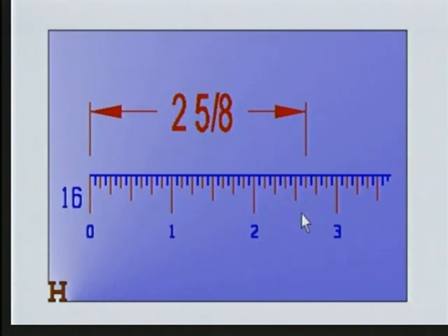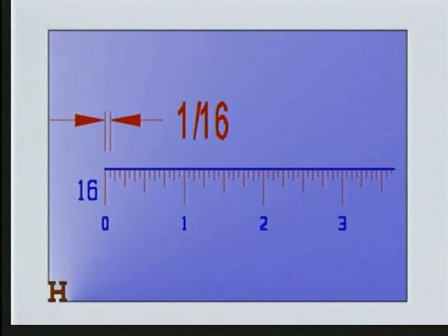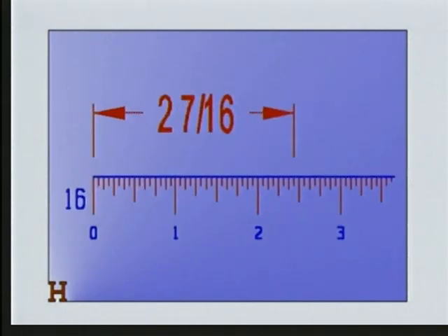And then we get to the smallest division on this scale, which is the 1/16 inch division, and there are 16 of those in each inch. And we can use that to measure something like 2 7/16 inches. Here's 2, and there are 2 16ths in every 8, so there's 2, 4, 6, and one more is 7 16ths. So you can use this for measuring 2 7/16 inches. But keep in mind, when you're looking at a basic inch scale, this number over here will give you the clue to the smallest possible division you can measure with it. Now, there will be some people who will take this scale and they'll tell you that they measured something that was 3 2/32 inch long, but they were guessing.